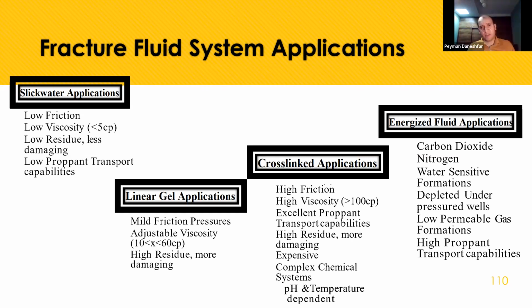And energized fluid applications, such as carbon dioxide and nitrogen, are for water-sensitive formations, depleted under-pressure wells, and low permeable gas formations, with high proppant transport capability. These are the differences between fracturing fluid system applications.